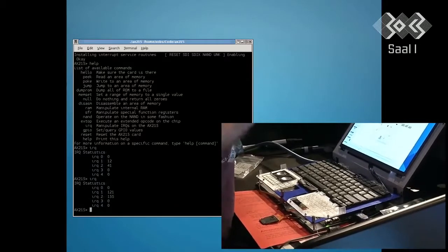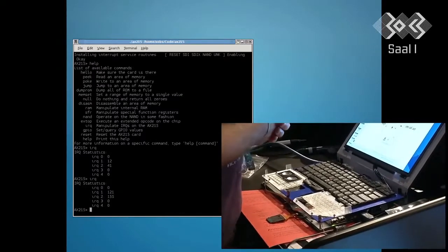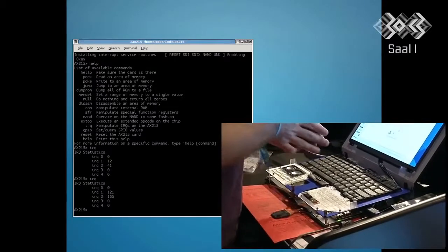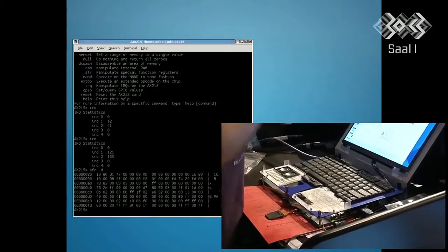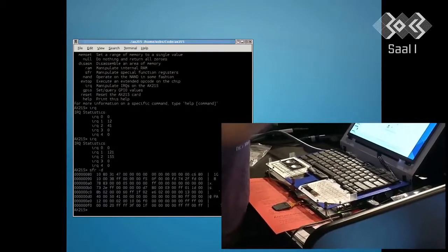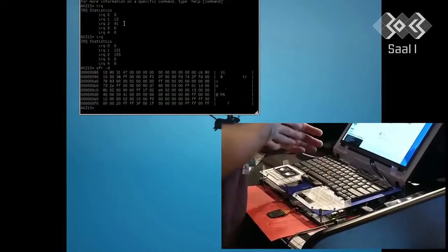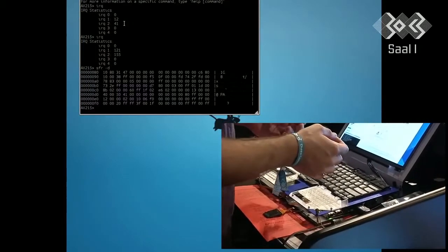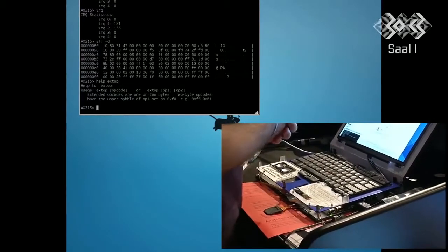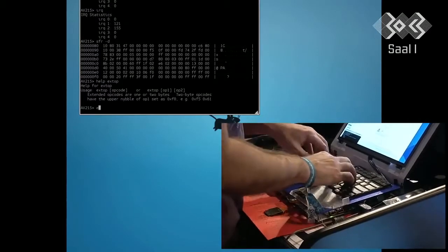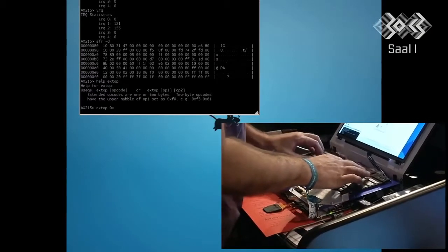Because these numbers keep going up, it means IRQs 1 and 2 probably have to do with the SD communication. Other things we could do is dump the special function registers. One of the nice things about 8051 code is that there are only 128 possible registers, which makes it really easy to fuzz. What else? There's also an external opcode command. I mentioned this in the talk, where you can have it execute an arbitrary opcode. So we'll send it A5 and then 1D.